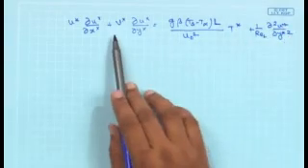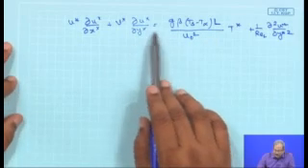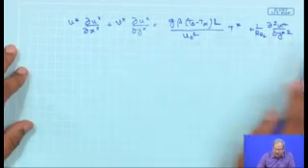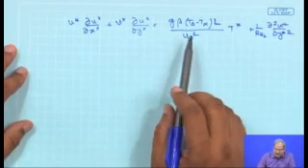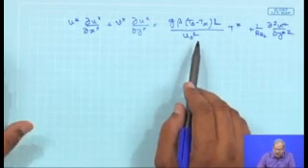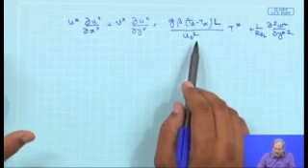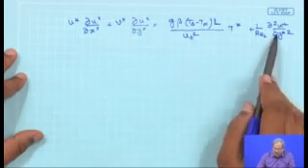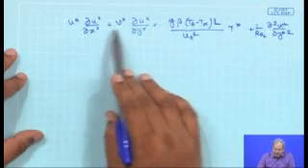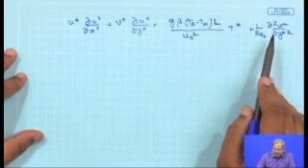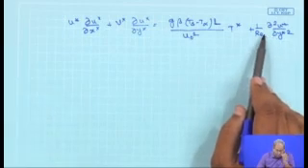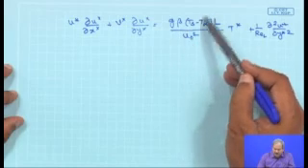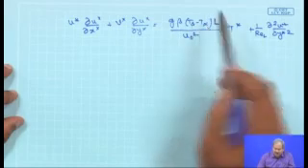Just see this equation and compare it mentally with what would have been obtained if there is no temperature gradient present in the system. If there is no pressure gradient and no temperature gradient, then this equation of motion would simply revert to the equation that we already know. The first term on the right hand side would be 0, since Ts would be equal to T infinity.